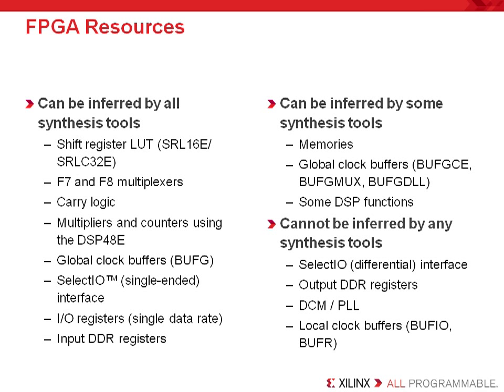One of the best ways to determine how to infer a resource is to go to support.xilinx.com and open the XST user guide. Now this is also accessible from the ISE software. You can get it there from the help menu as well. And then do a search for SRL coding techniques, and you'll find examples of how to infer the shift register LUT. Now this user guide provides numerous examples of a wide range of dedicated architecture resources in the FPGA and shows you how to infer the best FPGA resources. So be sure and check out the XST user guide.